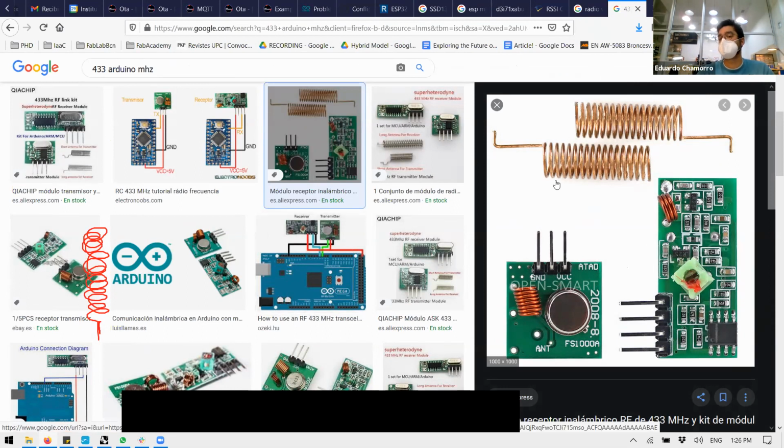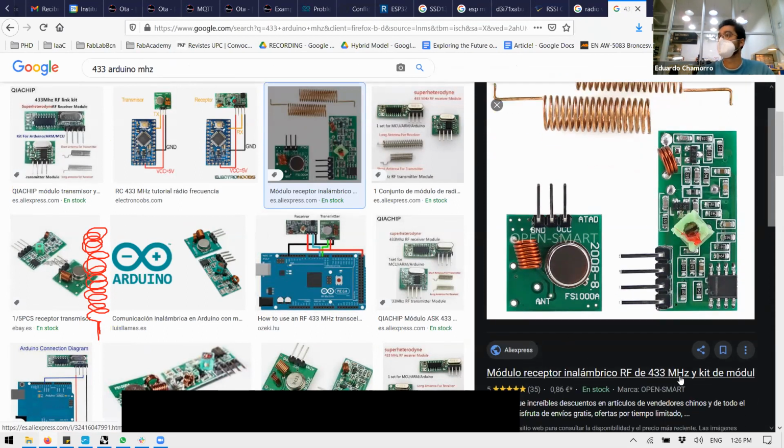These devices usually emit at 433 megahertz. The antennas, if you elongate this, will measure something around 15 centimeters. You don't want a remote of 15 centimeters. So actually what you do is produce a spring to have the same length of antenna, but in a smaller package. Are you reducing the sensitivity of the antenna? Yes. But the cost is you can't fit it everywhere.